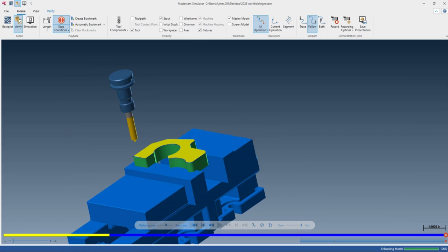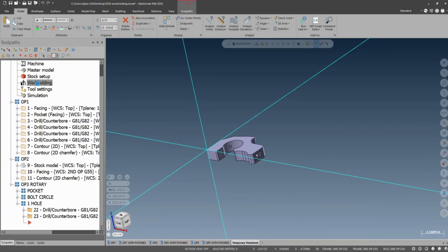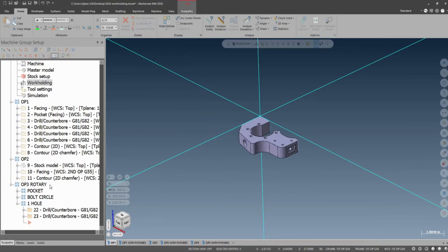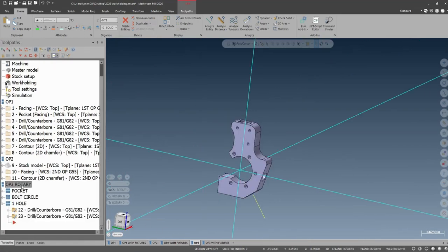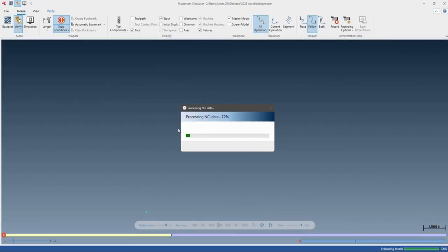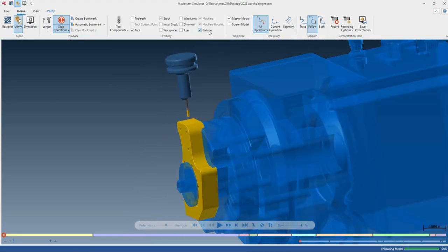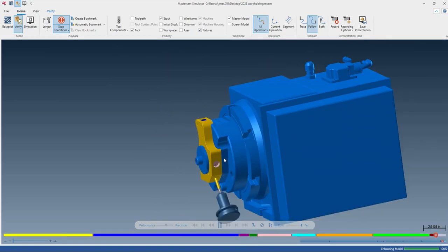And lastly, I'll show you the op 3 one. Again, it's exactly the same procedure. Set your workholding initially, so op 3. And set your WCS. And there's my thing that I've selected. I'm going to press play. And essentially it'll load up my fixtures, and again, they are fixtures. And you can set it up for collision checking and all that kind of stuff.